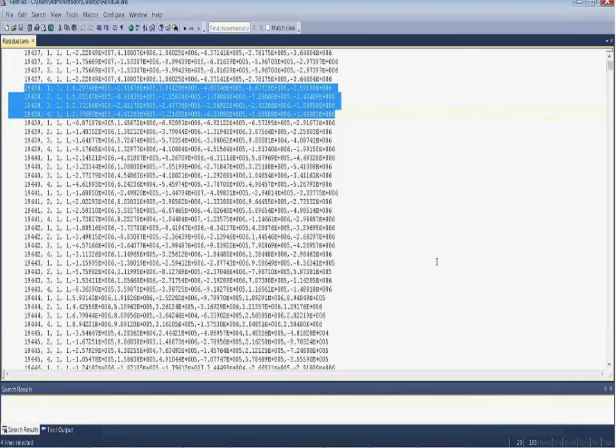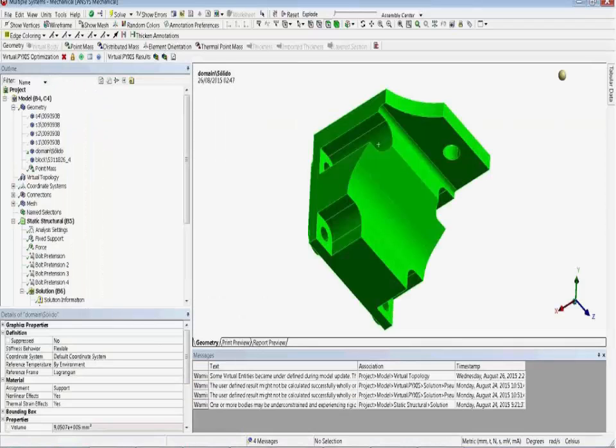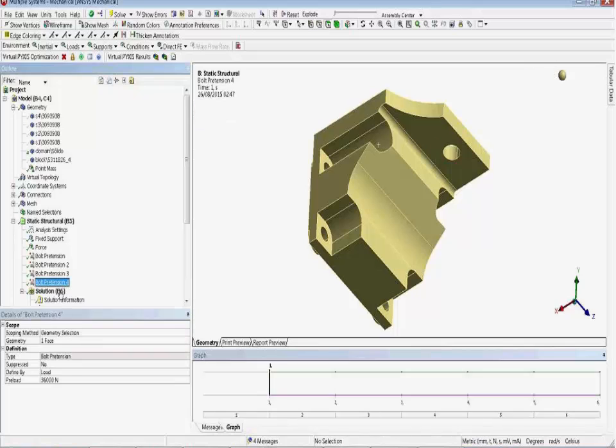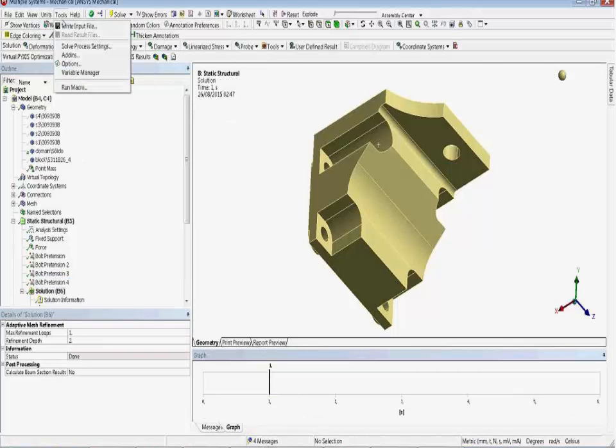We export the mesh, and MAGMA runs its own mesh, and at the end, MAGMA interpolates the MAGMA mesh result to the mesh that we exported using this command of ANSYS, solution write input files.